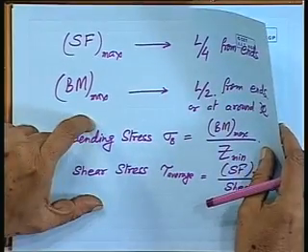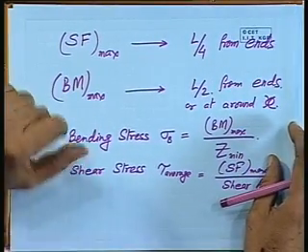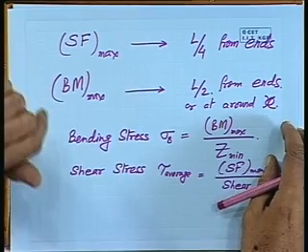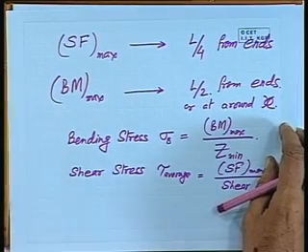Now, this is what we would like to find out, and this we should calculate for those 6 loading conditions or those 6 defined conditions at least, and whatever is the absolute maximum stress for the shear and for the bending, that we will say is what we expect to be the maximum during the 20 years life or the expected life of the vessel, and that stress value we will check against the permissible limit of the material.